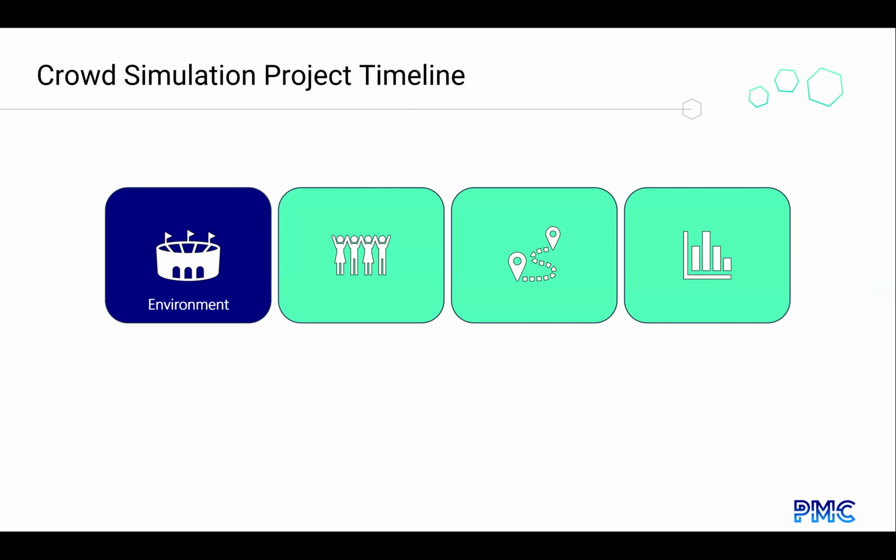We like to say that there are effectively 4 major steps to analyze a crowded environment through simulation and to answer key questions about things like its safety and its operation. So we start with the environment. When drawing up or importing an infrastructure from CAD or BIM, one needs to define, for example, the width of paths, locations of crossings and other interaction points, and the location of critical elements such as stairs, escalators, elevators, etc.